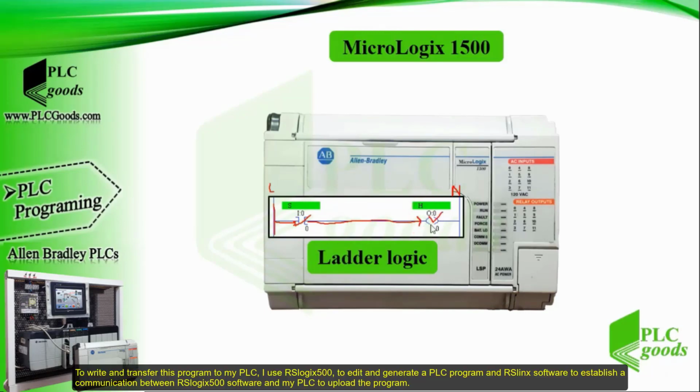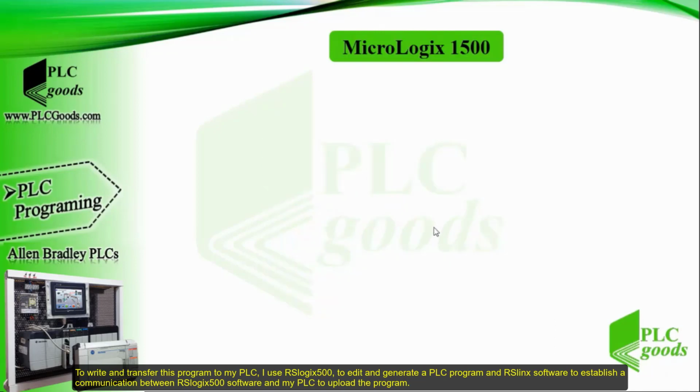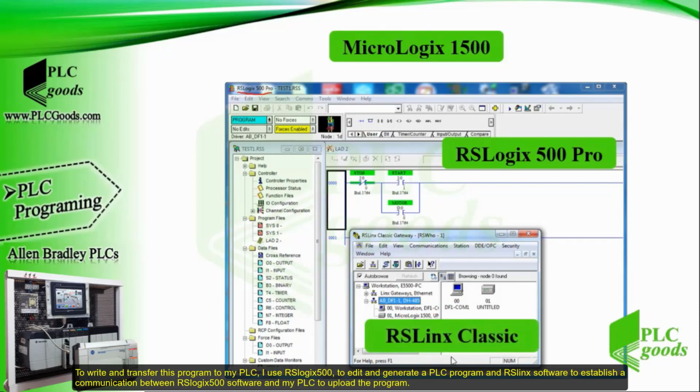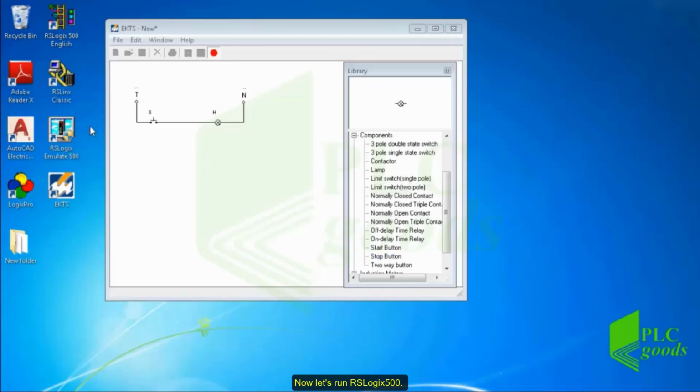To write and transfer this program to my PLC, I use RSLogix 500 to edit and generate a PLC program, and RSLinx software to establish a communication between RSLogix 500 software and my PLC to upload the program. Now let's run RSLogix 500.